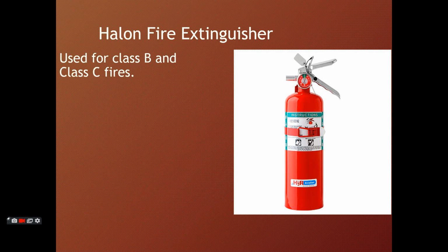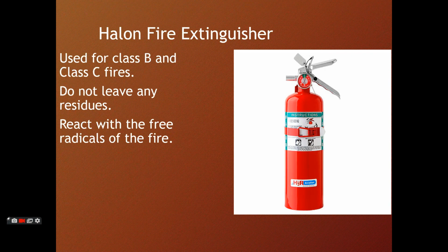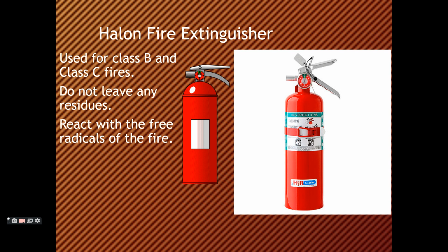After that we have the halon fire extinguishers. Halon fire extinguishers can be used for class B and class C fires. They do not leave any residues when you use them. They react with the free radicals of the fire. So this is your halon fire extinguisher. Normally you will not see it in most areas. Normally you will see only the A, B, C and D type of fire extinguishers.